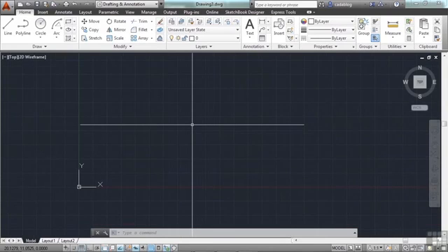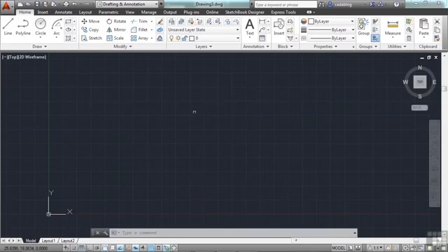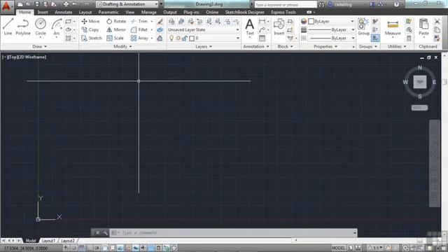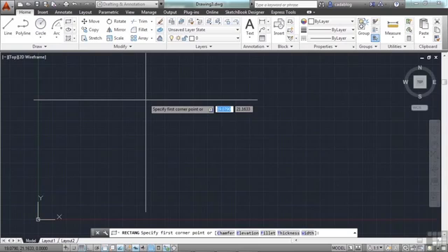So in this drawing, again, we're going to create a basic, very simple landscape plan view of our home. We don't have any numbers to go by or anything specific, so I'm just going to provide you with those. First, we're going to draw the outline of our house, and we're going to make it with the rectangle command. A lot of times, the landscape architect will have nothing more than just the outline of a house to design around. So start with the rectangle command. You can pick it here in the Home tab in the Draw panel on the ribbon, or you can type in rectangle or just REC.